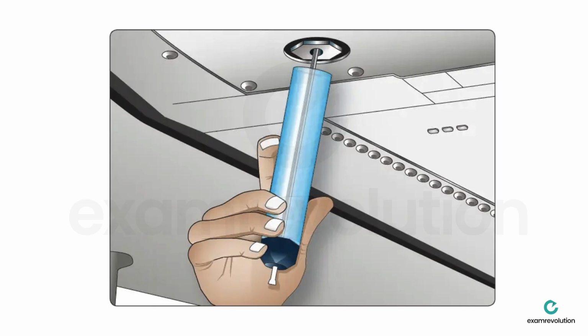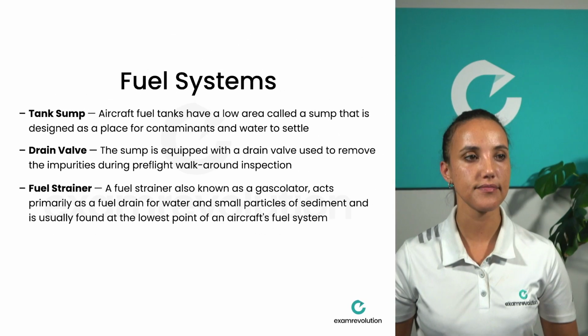So when the fuel has settled, the water and sediment or solid particles are heavier than fuel, so they will settle at the bottom of the tank and move to the lowest point of the tank, where you are able to drain and check for any impurities.